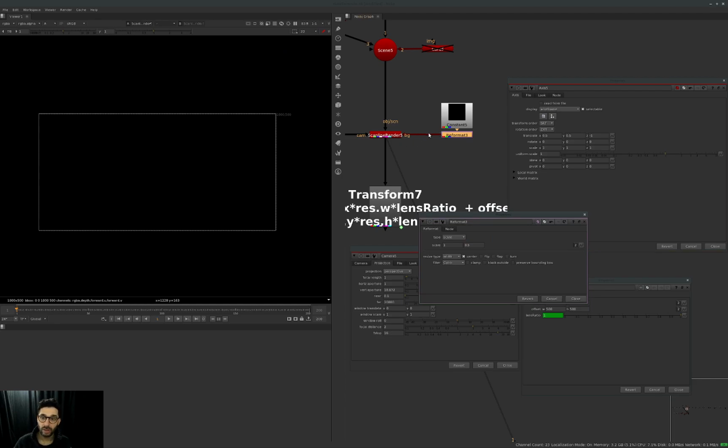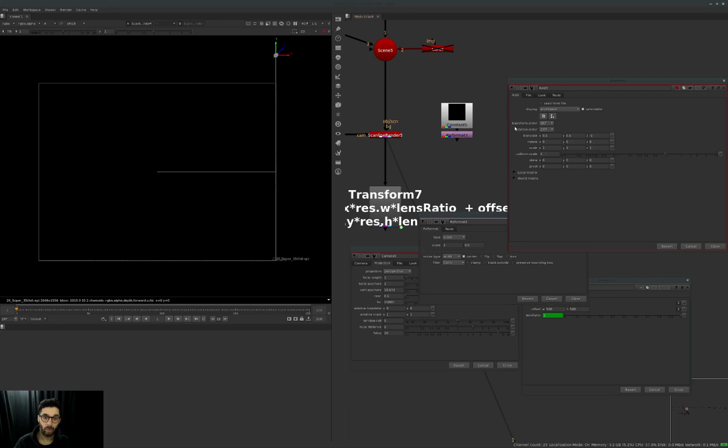If I would take it out, then it would be driven by the project. And by the way, you can still see that it's still half over here. So the resolution doesn't define anything in the 3D system. It's just a scaling factor. This is still going to sit on the half, no matter which format is over here, in this specific FOV of 111. In this specific case, no matter which format I put in, it's just a scale factor for it. It doesn't care.